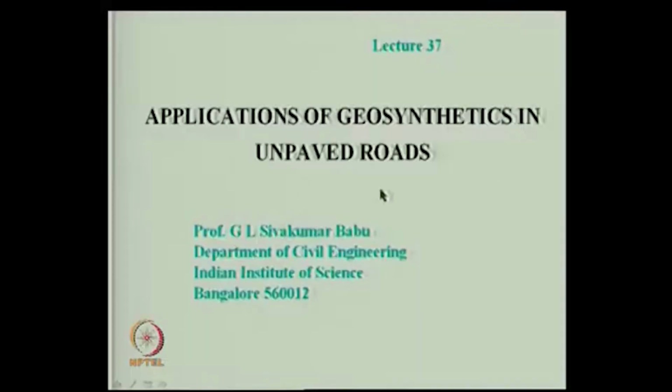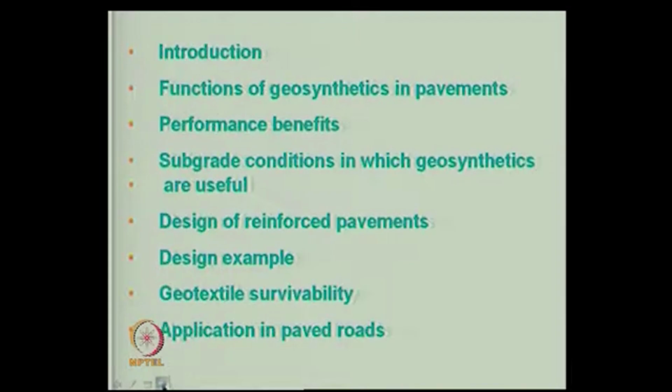We will be talking about applications of geosynthetics in unpaved roads in this lecture. When the soil is poor and you want to design the road, you do the CBR test, which is nothing but a strength test, and we try to see that the thickness of the pavement is arrived at based on the CBR value.